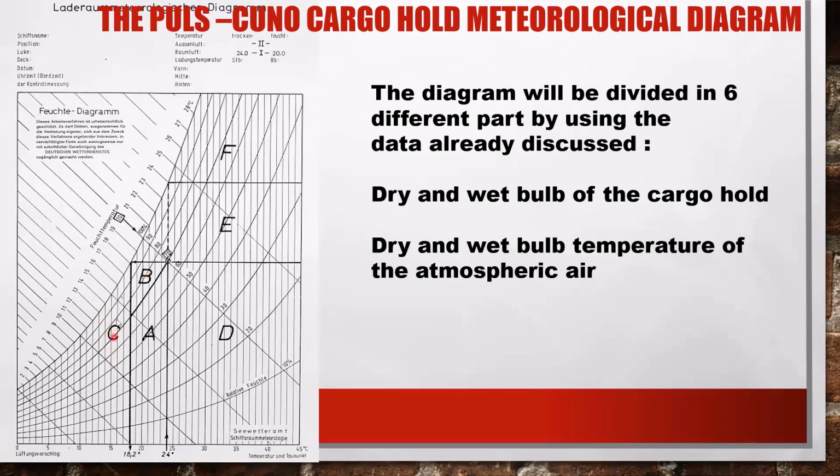If it is in field C, then slight ventilation shall be done to avoid sweat at the ship's construction. The holds are to be checked very frequently because wet water can develop at the surface of the cargo near the ventilation opening. If it is in field D, it's only possible to dry but not to cool the cargo. Probably it will warm up and biological reaction will be encouraged. A drying effect is reached even if the ventilated air is cooled down to cargo temperature.